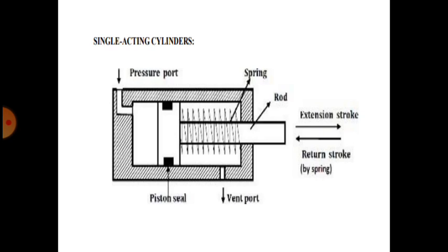This fluid power in turn is converted back into mechanical energy to do the work by hydraulic actuators and motors. The power developed at the actuator depends on the flow rate, the pressure drop across the actuator, and the overall efficiency.